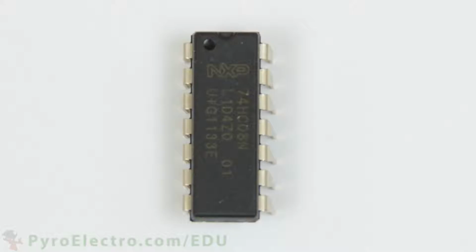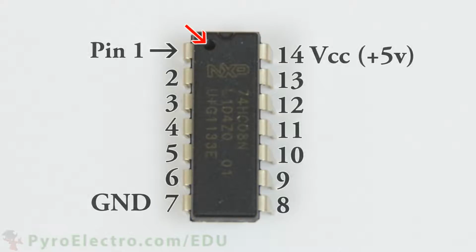The 74HC08 IC is a quad AND gate device. This circle can be found on any integrated circuit chip. It tells you that pin 1 is right next to it. From that point, you can count out the identification of each pin as you see on your screen. For the logic ICs we'll be using, pin 7 is always ground, and pin 14 is always plus 5 volt VCC.